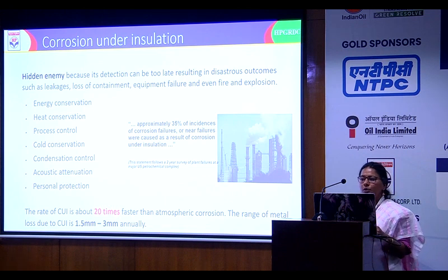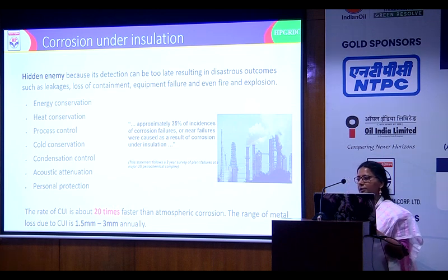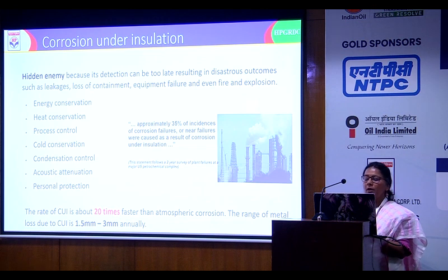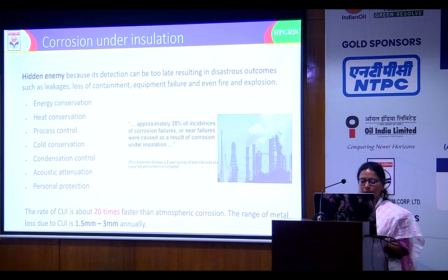Now, why insulation? It is mainly from an energy conservation point of view. Somewhere even heat conservation is required, or process control, like we have to maintain temperatures above the dew point. That is why we have heat tracing, over which we need to have insulation. Then it is also used for cold conservation and condensation control. Sometimes it is also used for acoustic attenuation, and of course, last but not least, reliability and safety, because there has to be a safe temperature.